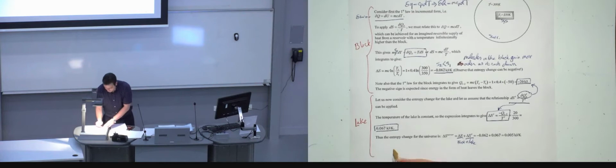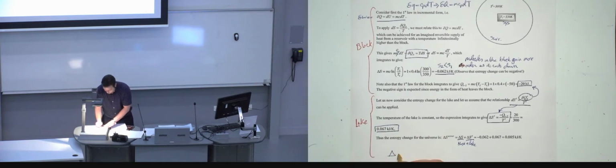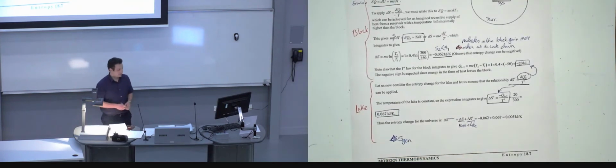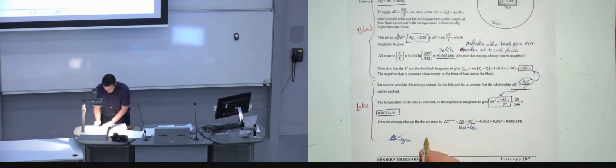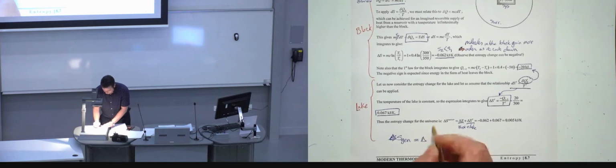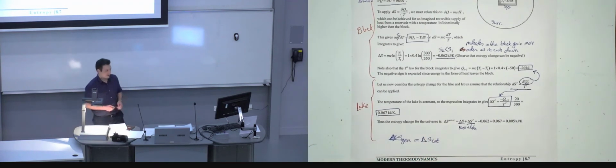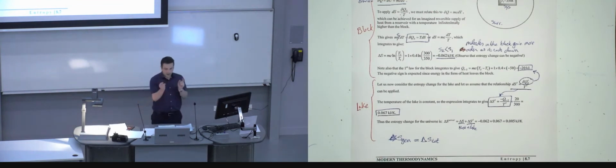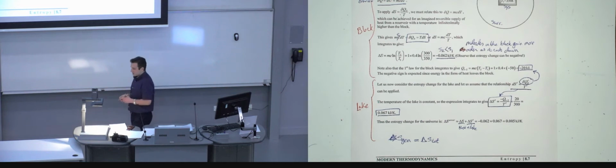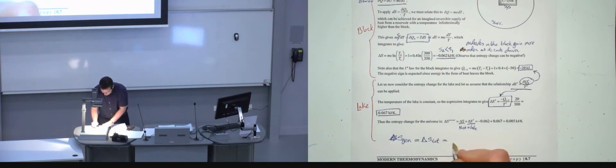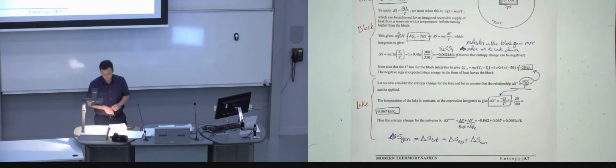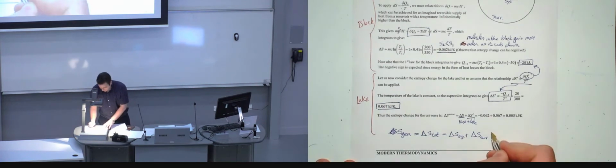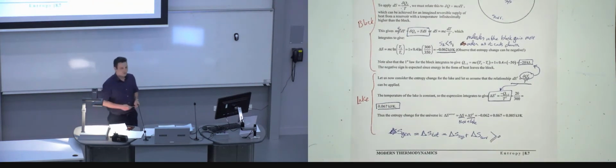So, in other words, we could write that if I want to talk about the generation of entropy, S-gen, it would be the total change of entropy. So the delta S total, if you do that, then you end up with how much generation of entropy you've had in the process. And that is really the change of entropy of the system plus the change of entropy for the surrounding, and that has got to be equal or bigger than 0.